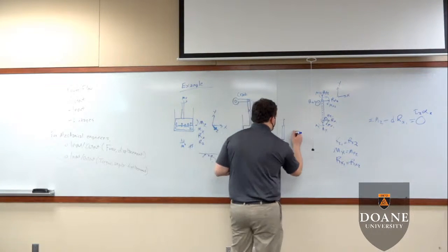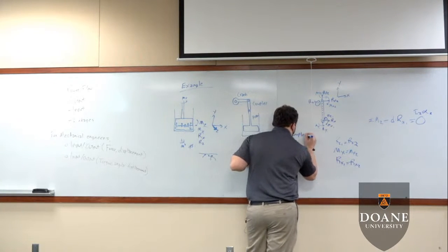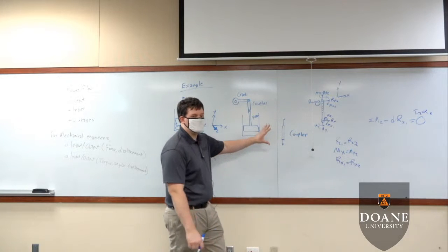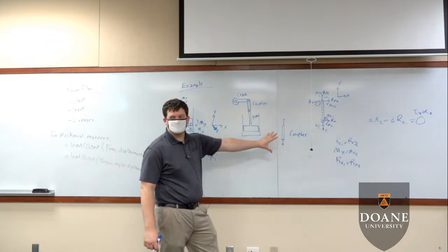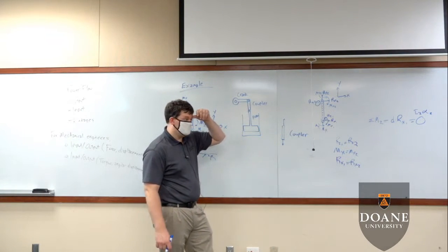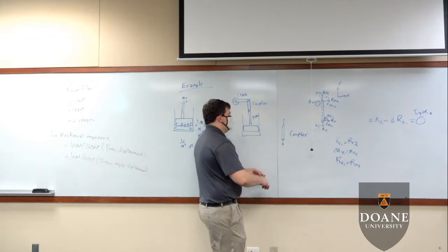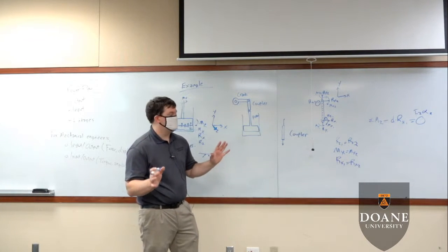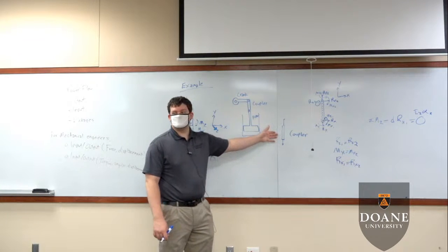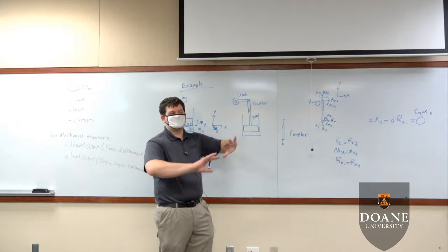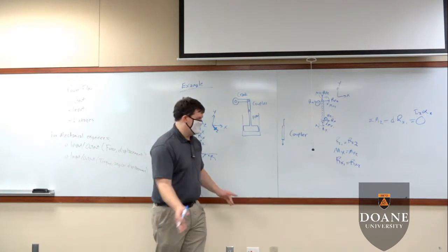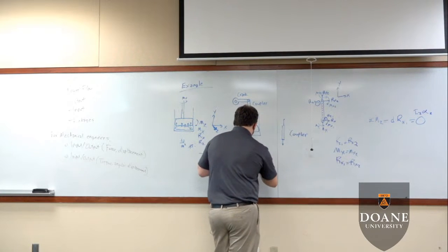Okay? But this is the coupler. And this is the total force that is being carried through the coupler, has to be in the vertical direction. Now we're going to take that knowledge, because this was our easy component that only has 2 revolute joints. That one's the easy one to figure out the vectors for. We're going to take that, and we're going to go back and look